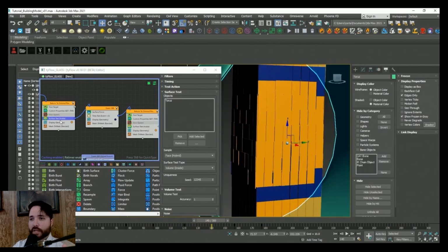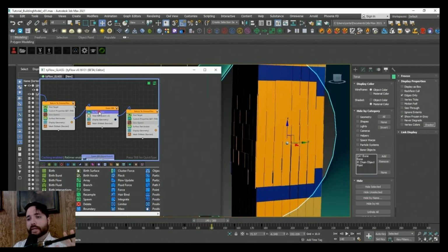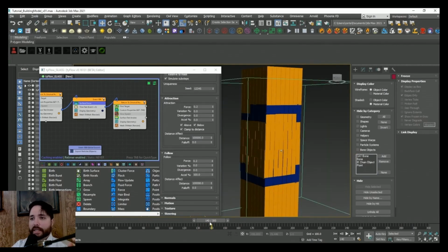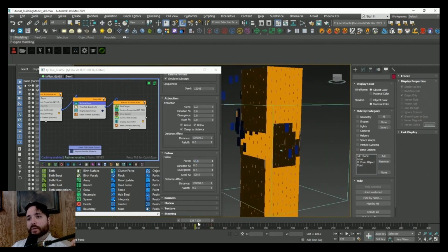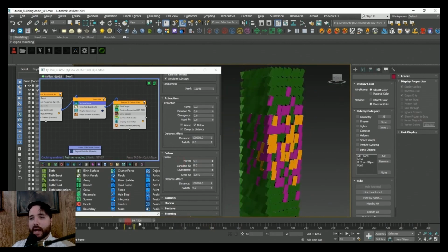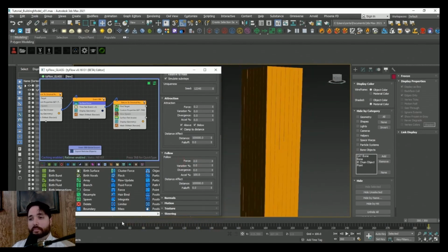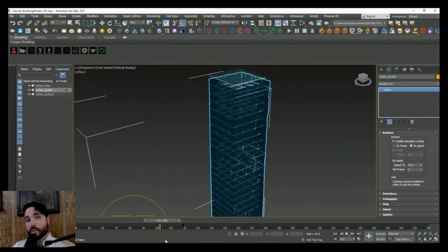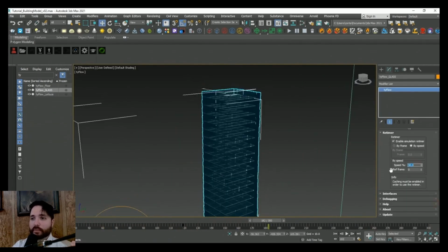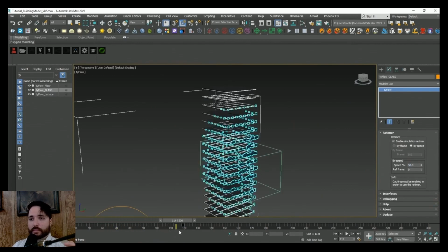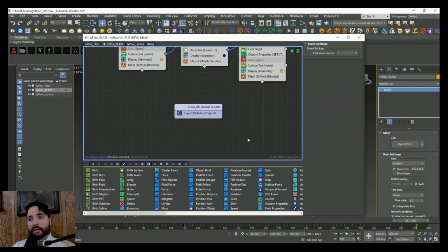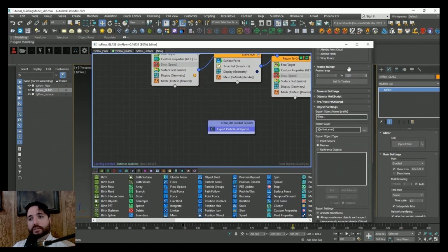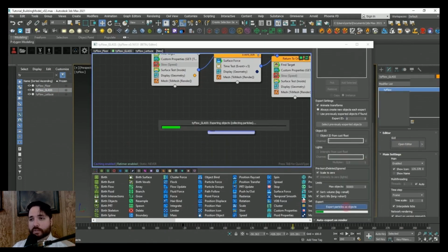Here you can see the windows highlighted in blue being pushed to a new event and getting affected by the surface force operator. By experimenting with the strength of the operator, we can increase the intensity of how much those window particles are offset from the impact. In my case, I kept the strength of the force operator fairly low, as I wanted to keep that ripple effect very subtle. Once that was done, I duplicated my TyFlow sim 2 more times, and I simply added my lattice and floor grid objects to them so that they would also react to the torus collider.